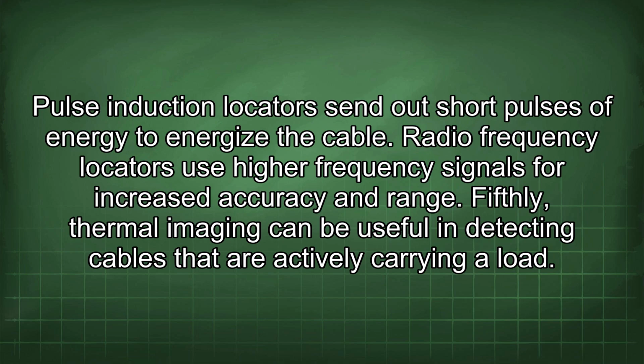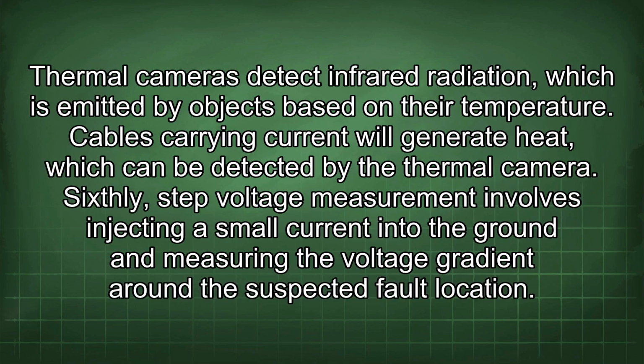Fifthly, thermal imaging can be useful in detecting cables that are actively carrying a load. Thermal cameras detect infrared radiation, which is emitted by objects based on their temperature. Cables carrying current will generate heat, which can be detected by the thermal camera.